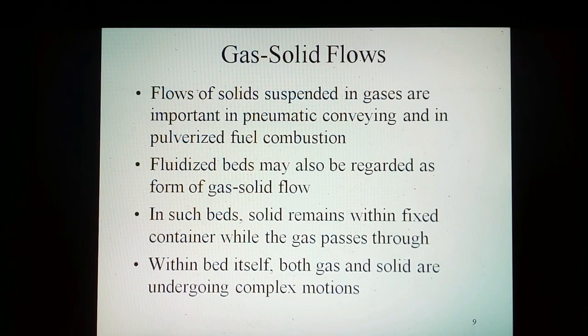Gas-solid flows. Flows of solids suspended in gases are important in pneumatic conveying and in pulverized fuel combustion. Fluidized beds may also be regarded as a form of gas-solid flow. In such beds, the solid remains within a fixed container while the gas passes through. However, within the bed itself, both the gas and the solid are undergoing complex motions.